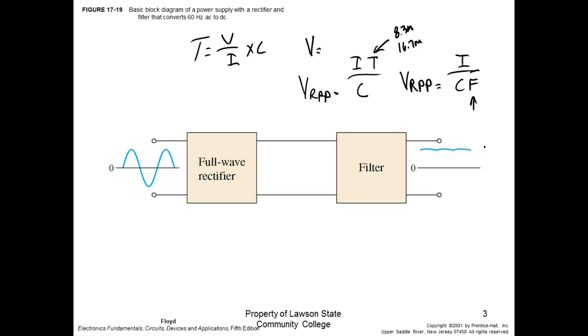So no matter what input frequency I give you, if it's half wave, the input AC frequency and the output ripple frequency are going to be the same. If it's full wave, it's going to be double. Then you can use this no matter what situation you get in. If you go over to Europe, what's the frequency there? 50. In some countries you can look at a frequency chart and see which ones are 60s and which are 50s. And there are some companies that have both 50 in a certain region and 60 in another.